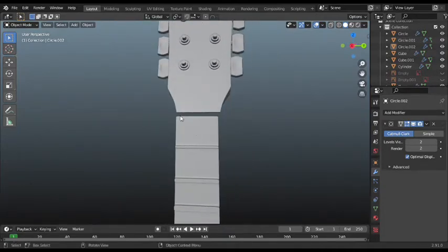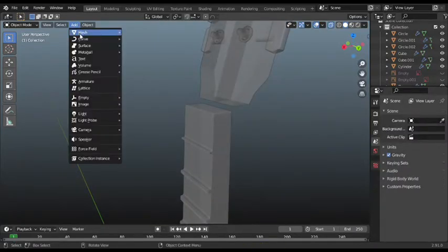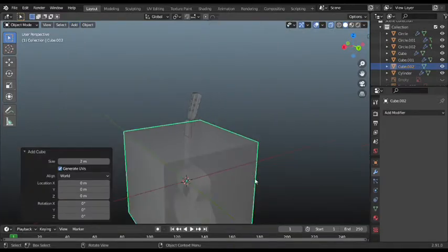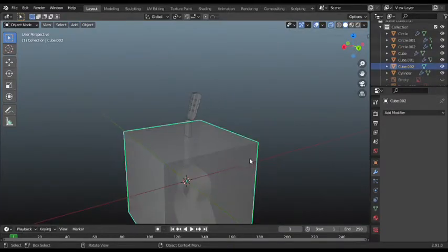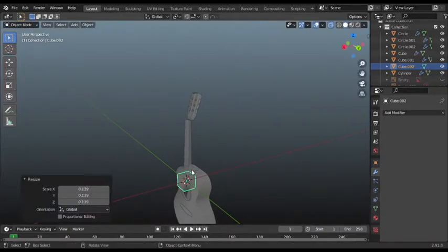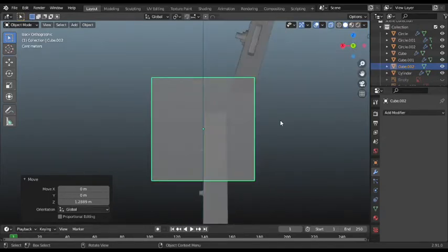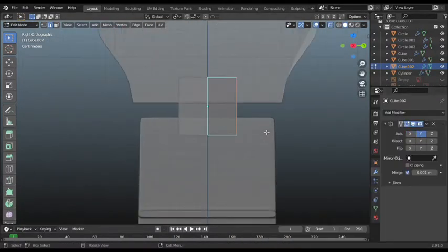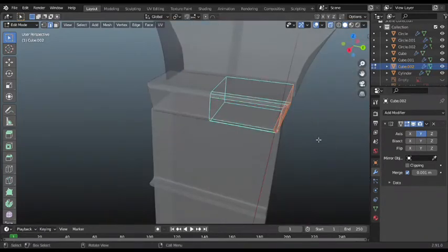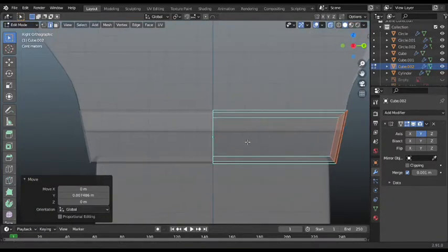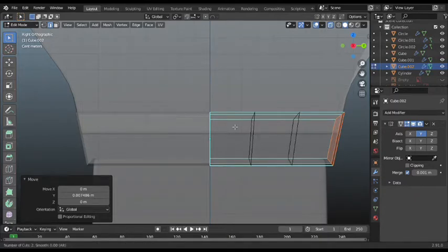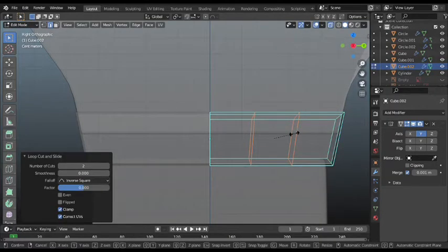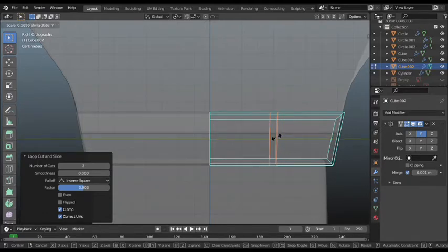so I'm gonna add a bridge up here which actually holds the wire, separates them from each other. For that I'm gonna add in a mesh and a cube. Scale it down, G Z, pull this up, yep, somewhere here, and I'll try to toggle the size. Okay, powery. Then I'm gonna swipe them about the y-axis to narrow the gap between the two. Good.